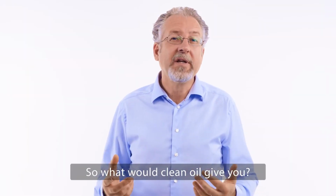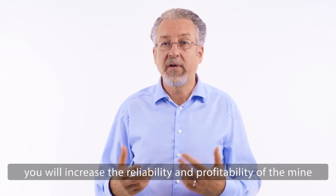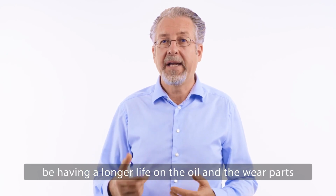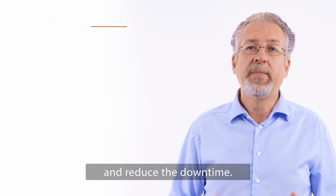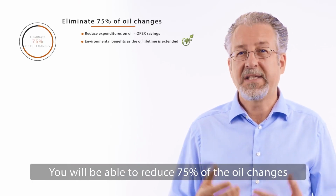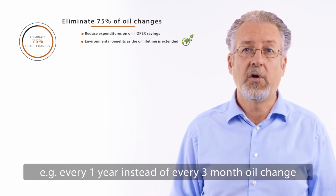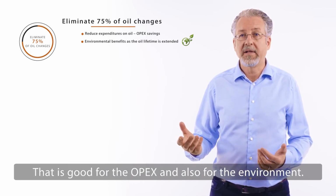So what will clean oil give you? You'll increase the reliability and profitability of the mine by having longer life on the oil and the wear parts and reduce the downtime. You will be able to reduce 75% of the oil changes. For example, every 1 year instead of every 3 months oil change on a crusher and mill. That is good for the OPEX and also for the environment.